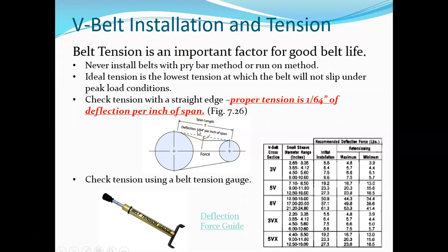So you can round that down to the lowest fraction, which is going to be 9/16: 4 will go into 36 nine times, and 4 will go into 64 sixteen times. So 9/16 should be the gap between your straight edge, represented by the dotted line, and the belt as it is deflected down. So 9/16. I'll show you how to use these.